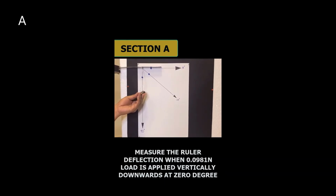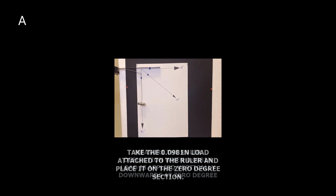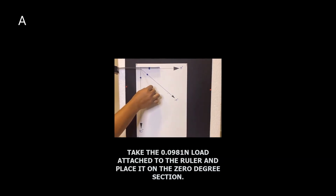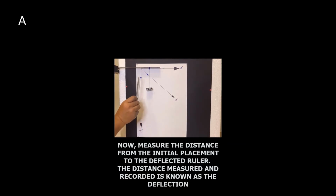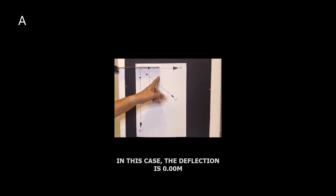For section A, I will measure the ruler deflection when 0.0981 Newton load is applied vertically downwards at 0 degree. Take the 0.0981 Newton load attached to the ruler and place it on the 0 degree section. Now, measure the distance from the initial placement to the deflected ruler, and the recorded distance is known as the deflection. In this case, the deflection is 0 mm.